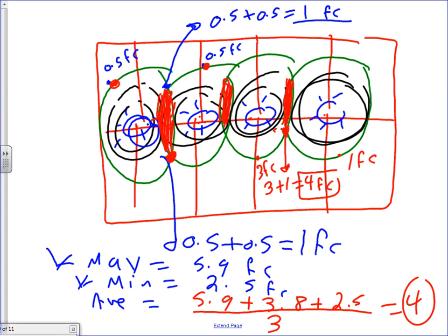Now suppose we have a parking lot, guys, and we have 1, 2, 3, 4 lights. Suppose that green is 0.5 and the green of the other one is 0.5. Right at the point where the two greens cut, what do you think the light from fixture 1 and fixture 2 are going to do to each other? Add up. This is why, when you grab the fixture outdoor in the parking lot and it has the isometric curve, I told you grab another one and overlap it. Overlapping will make them add up. So the green line is 0.5 isometric curve for each one of them. Where the two cut each other, you get 0.5 plus 0.5 equal what? 1. Can I have thumbs up, Chad?